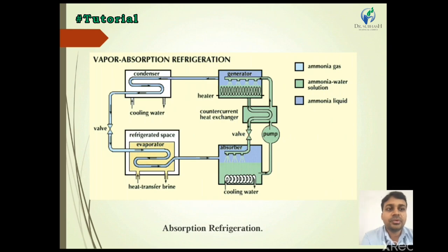First is ammonia gas and second is water. Ammonia is the main refrigerant in a vapor absorption refrigeration system, and H2O is the absorber. There is no requirement of any high pressure elements, meaning the compressor. Only a minor pump is required, and the system works smoothly.